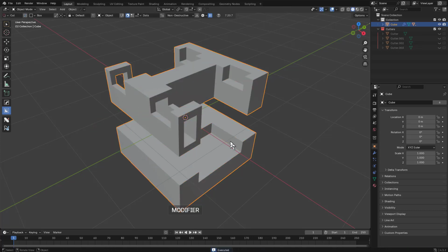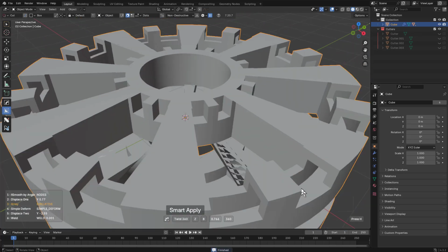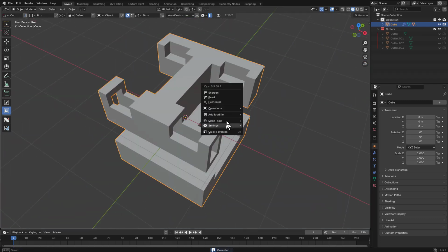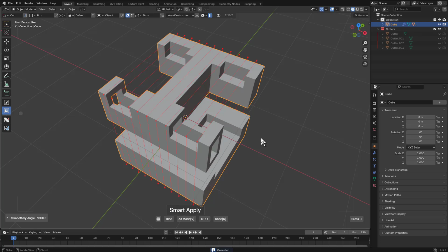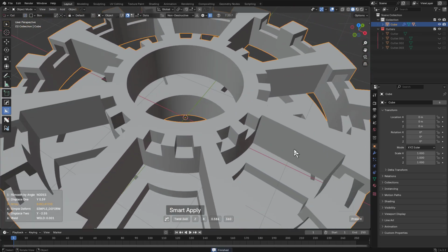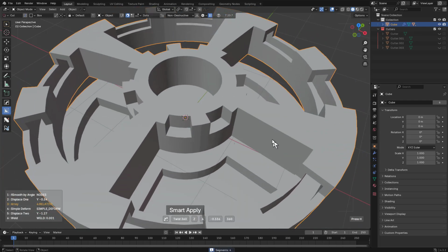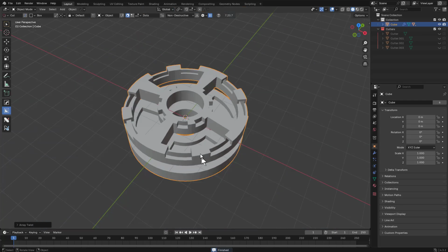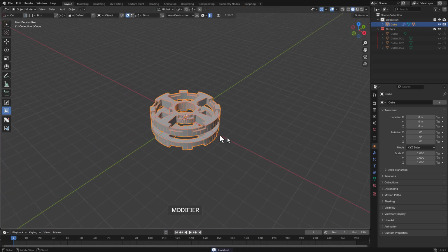And then we can mirror this to the other side, dice it, twist it, roll it down to low segments, but we see that that one didn't work out. So let's undo that and let's dice again. But this time, let us press Q to change the algorithm. Let's press T, and now we see that it goes through. So sometimes dice will have an issue, and it requires that projection is the algorithm used, but just like that, we were able to perform our maneuver.